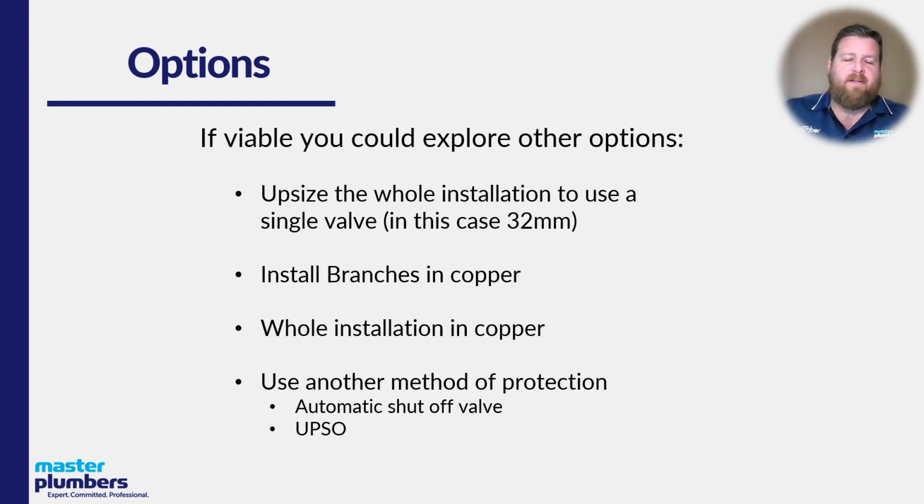Now, we've been getting some feedback, obviously, and we're not oblivious to the fact that copper is dearer than multi-layer, but each individual company or plumber needs to do the cost analysis for this, because by the time you buy the valves and the adapter fittings and install them, it may work out better off for you. And then there's a couple of other methods of protection, which is your automatic shut-off valves that can be linked in with the smoke alarms, or you can use an UPSO, the under pressure shut-off.